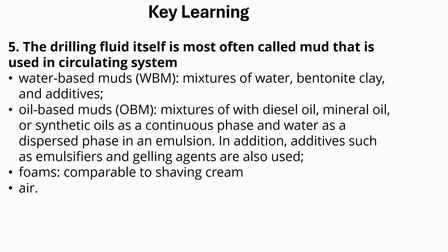Drilling mud lifts and suspends cuttings, stabilizes the borehole, controls formation pressure, deposits filter cake, minimizes reservoir damage, cools and lubricates the bit, transmits pressure signals for LWD and MWD tools, and helps minimize environmental impact. This slide is extremely important because drilling fluid is involved in almost every major drilling function.